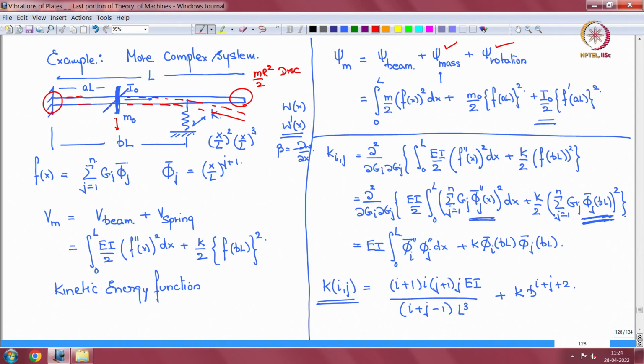Now we are looking at rotations of this form, rotation of the disk of this form. So that is the disk, then it rotates like this, and the beam deflects. So now the mass moment of inertia about this axis that goes into the board is half of that. That is why it is I0 by 2. So that it is actually m r square by 8.